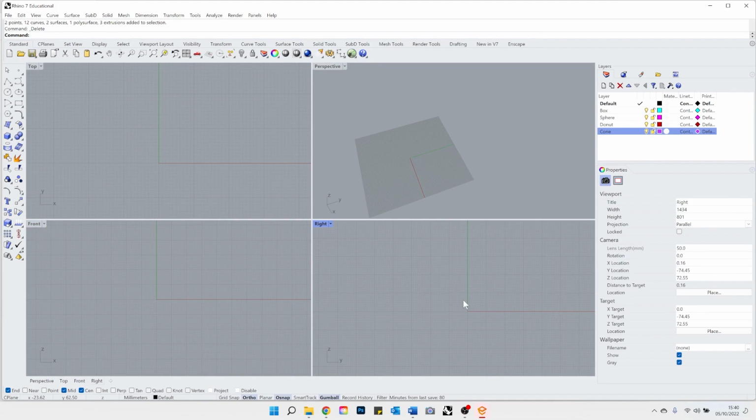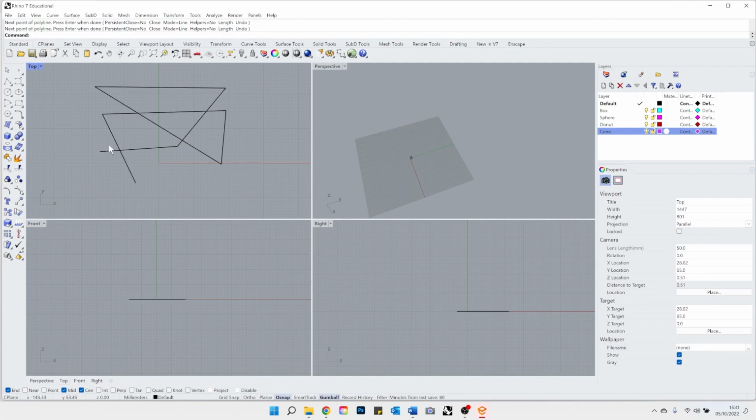Okay, so the main different types of geometry in Rhino that you can be using. The beauty of Rhino is that you can be working in 2D and in 3D as well. So for 2D tools, you have all your options on top here. You have your points, you have your line, or you have your polyline. Make sure that your ortho is off. It's the same thing as, for example, in AutoCAD, you have your polyline, and until you press enter, it's going to continue drawing.